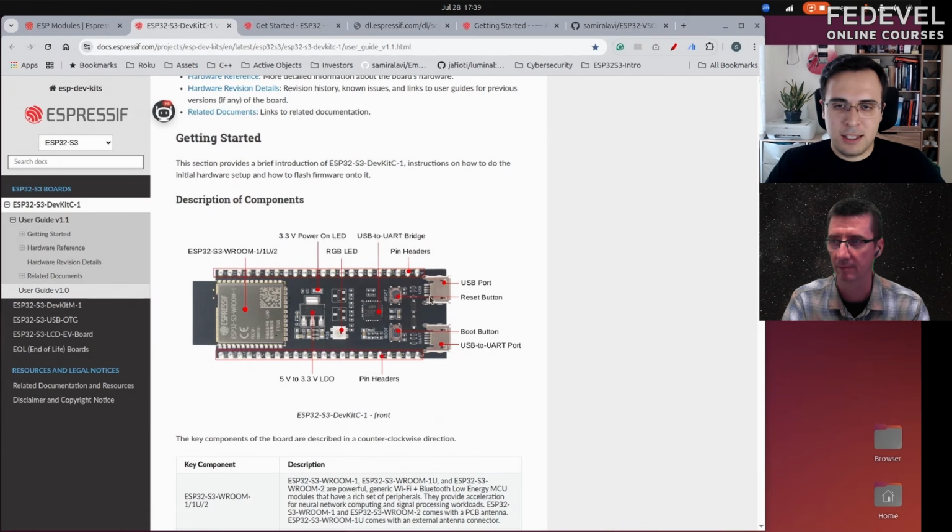And then this is the power LED. Then there is a USB to serial connector here, the USB to UART. The good thing about ESP32 is that it works based on UART. To program the device, it uses UART. And if you want to use a debugger, you can use a JTAG debugger. It provides a JTAG interface, but the UART interface also gives you the debugging environment using OpenOCD. So you can basically track line by line using the GDB debugger.